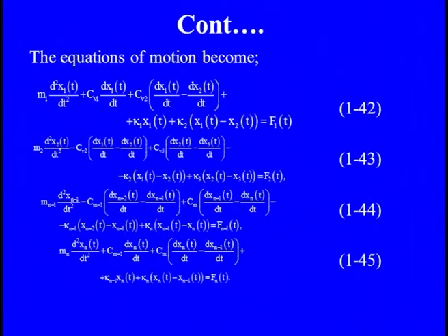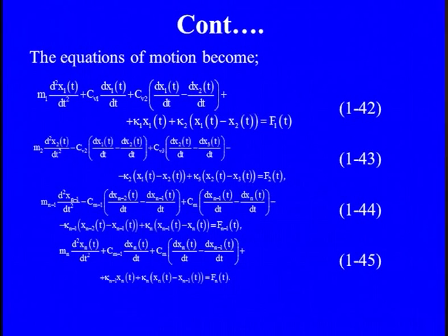So for that we need to apply a force factor, and we need to put the entire thing equal to 0 to get the eigenfrequency. In our equation we have two main factors, one is the damping and one is the stiffness, and if we want the system performance in terms of the eigenfrequency, then first we need to keep the damping factor 0 to get the undamped natural frequency, and if the damping is there, certainly we have the damped natural frequencies. So first of all we need to keep this force equal to 0, because the eigenfrequencies always come for free vibration conditions.